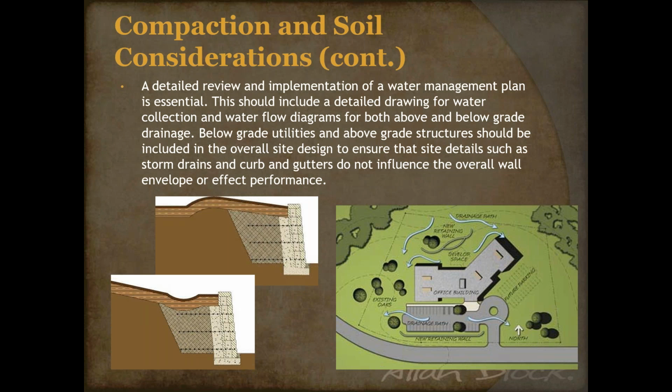And there are some scenarios where these might be a little bit higher. For instance, if there were an alternate drain, which we call it, you might have those drains moved up to above grade because you don't have anywhere to exit them at the face. And if that were the case, you put a low permeability material beneath there, so that the water sort of benches off at those drain pipes. And I should add an image in here for those of you that haven't seen that. But if anyone's curious about our alternate drain, you can definitely reach out to me after I follow up with you tomorrow.